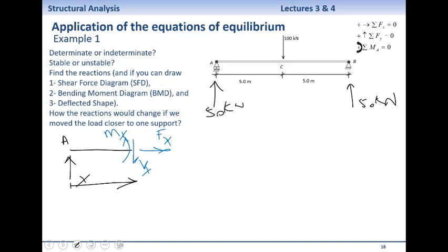Some of them may turn out to be zero, but potentially we have them. It's similar to the reactions that we just assumed. The horizontal reaction at point B turned out to be zero. And I know that the force here is 50 kilonewton. Only because I don't have enough space, I just get rid of the units. But you always jot down the units as well.